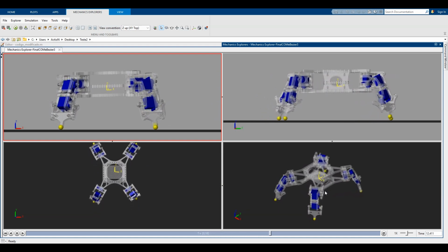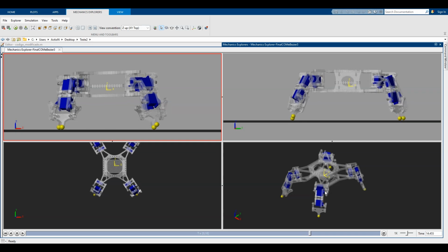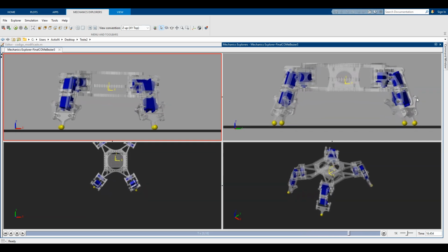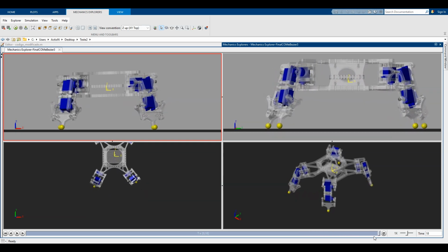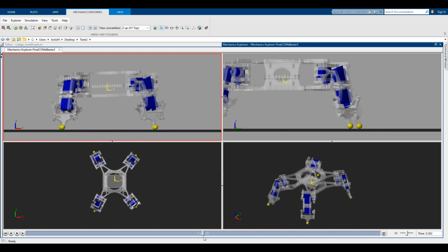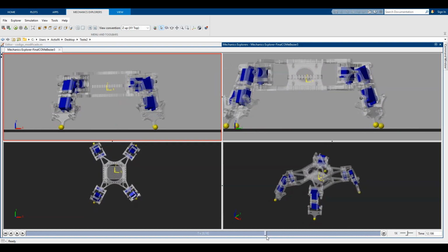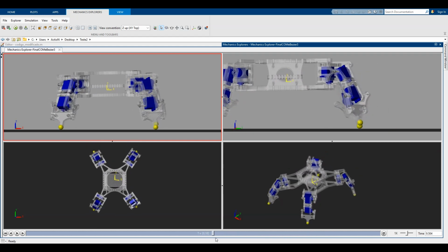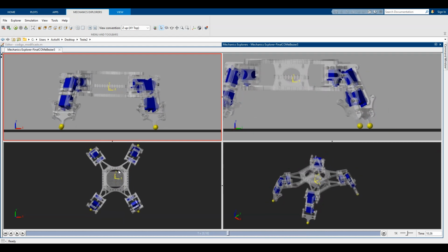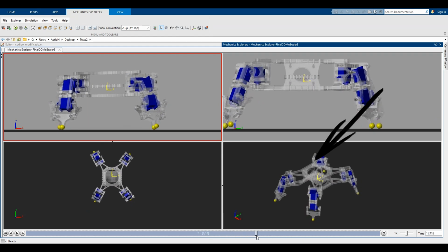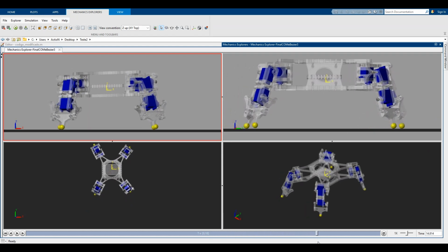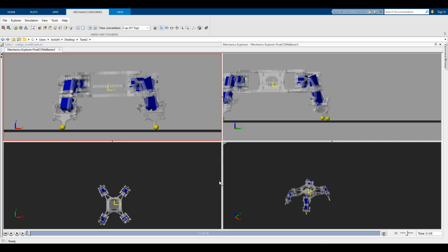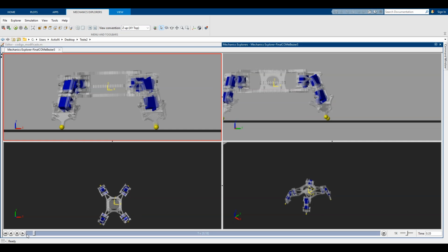The gait is carefully synchronized across all legs, ensuring that at most one leg is in the swing phase at any given moment, a defining feature of the crawl gait that enhances static stability. Multiple camera perspectives are used in the simulation to visualize the robot's motion from different viewpoints, including side, top, and isometric views. These perspectives highlight the coordinated movement of the legs, the tracking of the planned foot trajectory, and the overall body stability during locomotion.